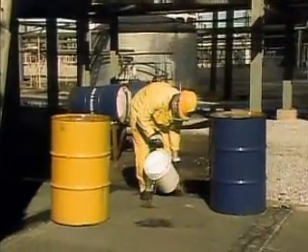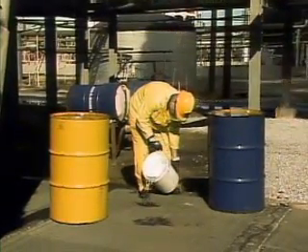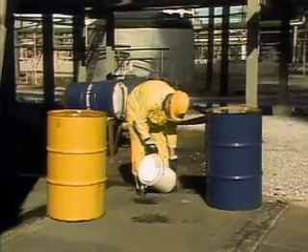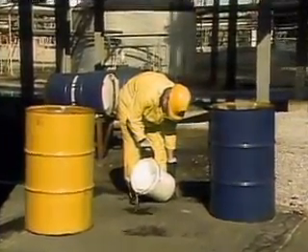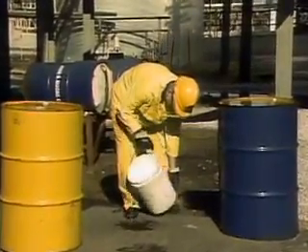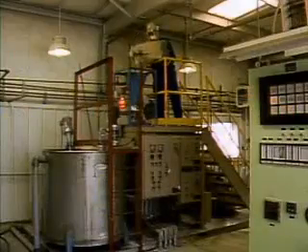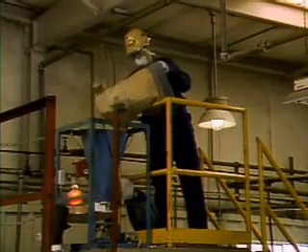Now, chemicals aren't always added with specialized equipment. Sometimes you have to add them by hand. If that's the case, you'll need to follow your company's procedures about where and how the chemicals should be added. For example, you may be required to add the chemicals near the makeup line so that they can be thoroughly mixed with the cooling water. Depending on the type of chemical that you work with, a face shield, rubber apron, gloves, and boots may be required to protect your body.